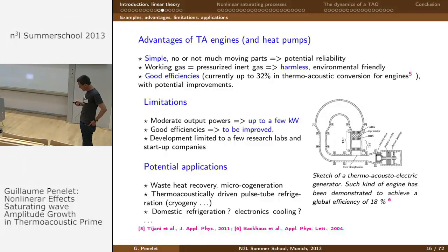And also, the development of these engines is by now limited to a few research laboratories. In terms of applications, one of the promising applications of these engines is waste heat recovery. So we can imagine, for instance, this kind of device. From the waste heat, we can generate an acoustic wave within this device, and this acoustic power can be transformed into electric power using a linear electrodynamic alternator. And such a device can achieve an efficiency of up to 18%, which is not so bad.